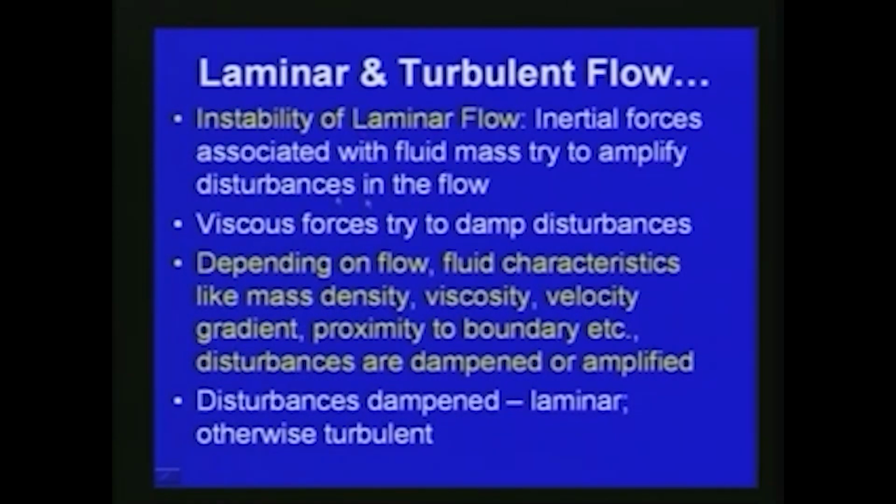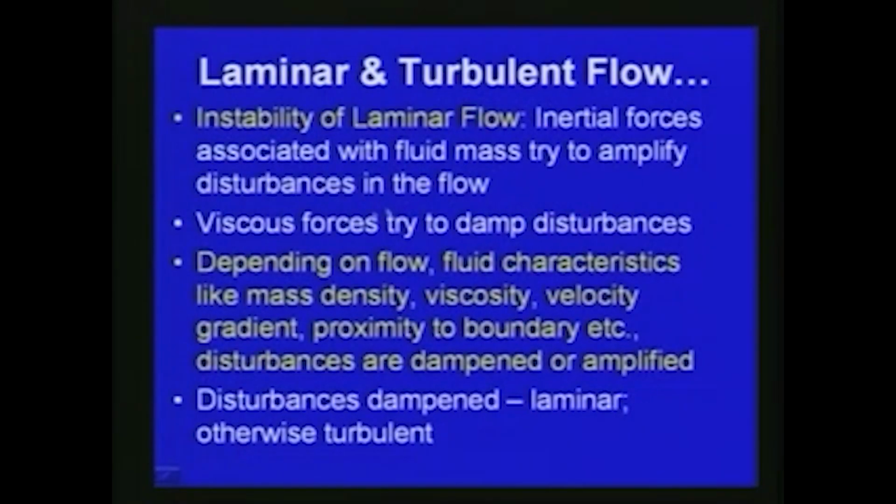Now, whenever we conduct these kinds of experiments in the laboratory, we can see that the laminar flow, which flows in layers, may at some stage show instability. Here the inertial forces associated with the fluid mass try to amplify the disturbances in the flow.